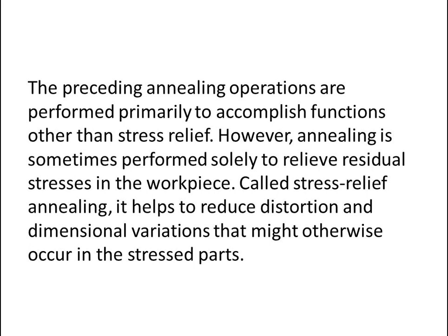The preceding annealing operations are performed primarily to accomplish functions other than stress relief. However, annealing is sometimes performed solely to relieve residual stresses in the workpiece. A stress relief anneal helps to reduce distortion and dimensional variations that might otherwise occur in the stressed parts.